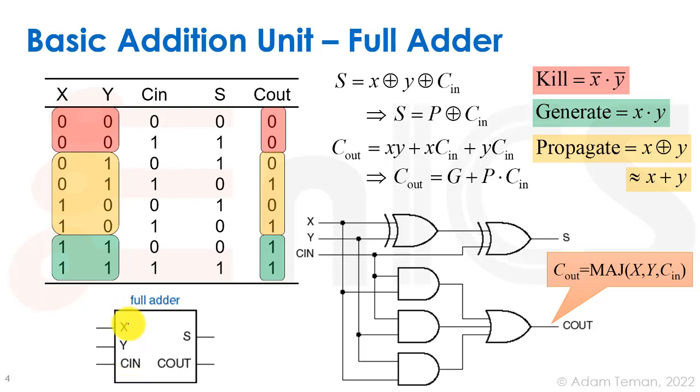There are 3 inputs to the full adder, right? And so there's this input and this input and this input. And what we're basically deciding by the output is how many ones are there. So we're asking how many ones are at the input. And the answer is going to be 2 to the power of 1 times C out, plus 2 to the power of 0 times S. So this is a binary encoding of the number of ones over here. If we get 0, 0, 0, for instance, then our answer is going to be 0, 0. There are 0 ones at the input. If we have 1, 1, 1, how many ones are there at the input? There are 3. So that's going to be 1, 1 at the output.